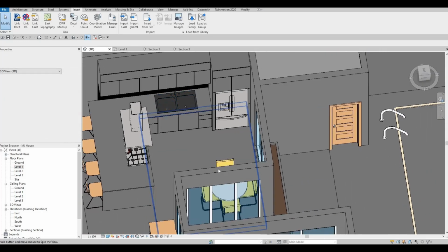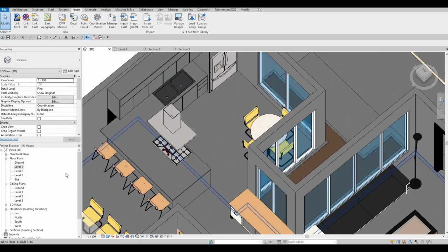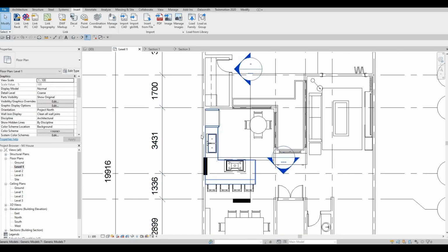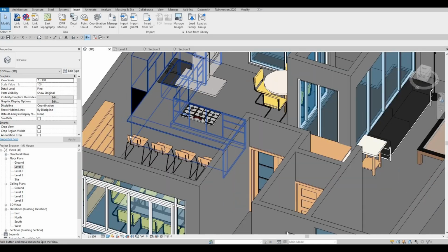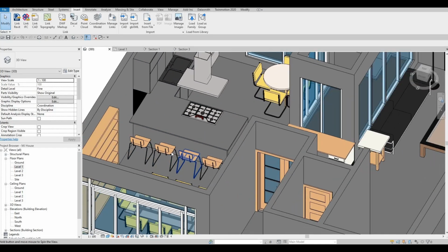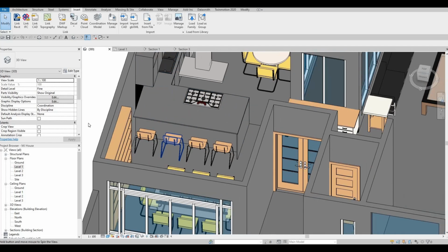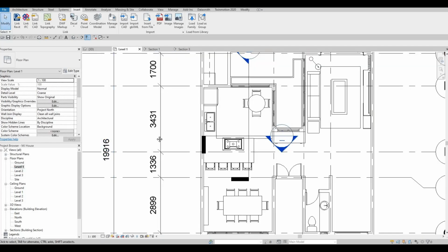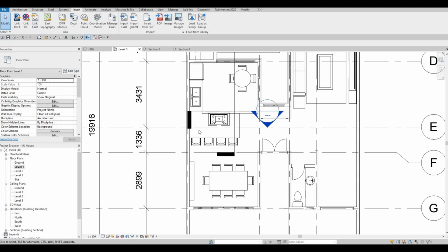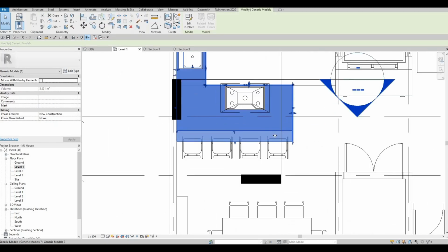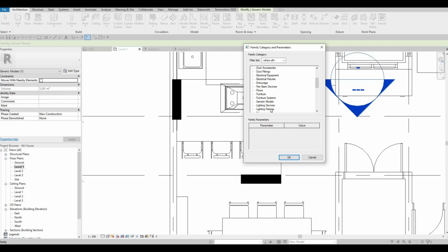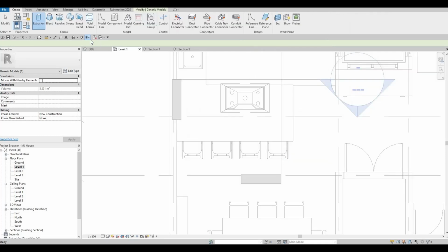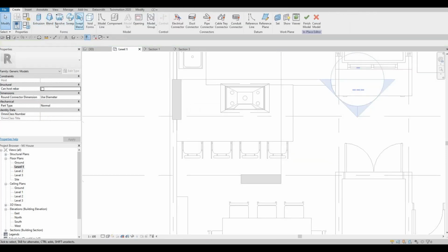So that's good enough to put it there. And then now I'm going to my 3D, and I want to just create a railing there, or a foot rail. So the way that I'm gonna do it is from level 1, and then here I'm just roughly going to estimate where it's gonna be, and then here I'm gonna model in place, generic model, and then I'm gonna create an extrusion.